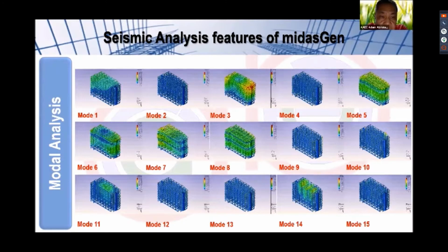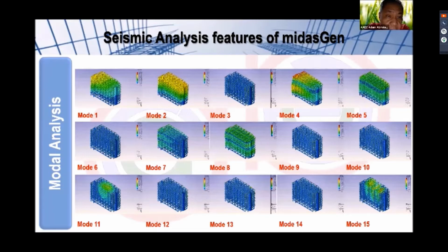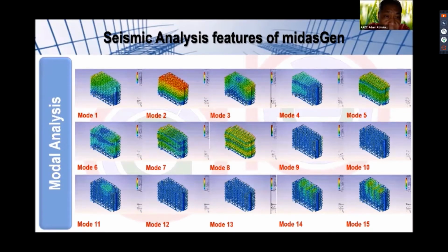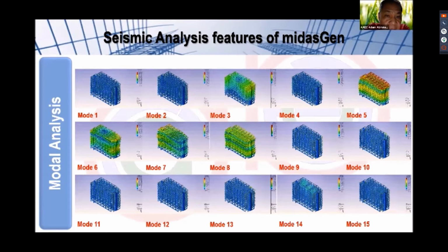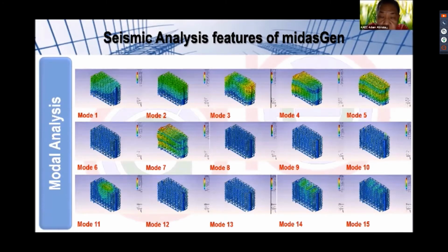So mode 1, which is the fundamental mode. Then if we try to look at the deformation animation of mode 1, the vibration is in the transverse direction, whereas mode 2 is in the longitudinal direction, whereas in mode 3, you already have the rotational displacements already.